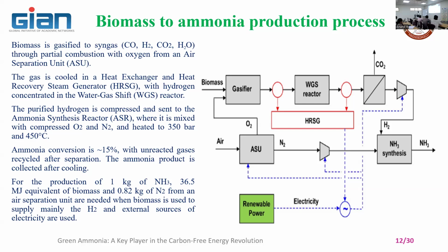Suppose you want to buy something, and the cost of the particular product is 100 rupees. If you have 100 rupees, you can buy it. If you have more than that, you can get the balance. If you have less, you cannot buy the product. That is not possible in combustion. In combustion, you can supply the exact quantity or a little more than that, so we ensure that the products of combustion are complete.